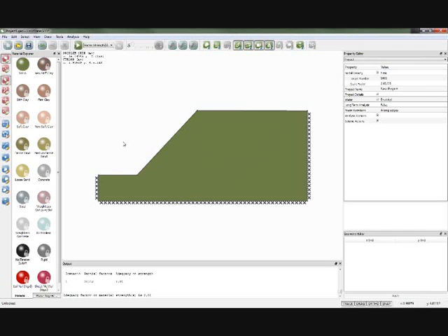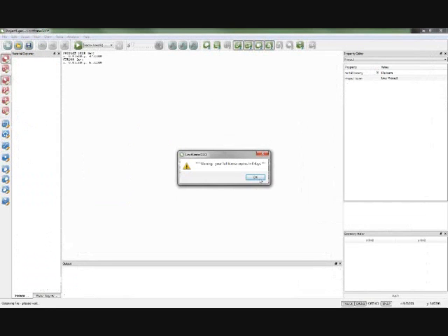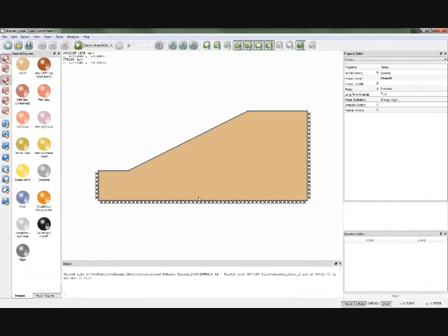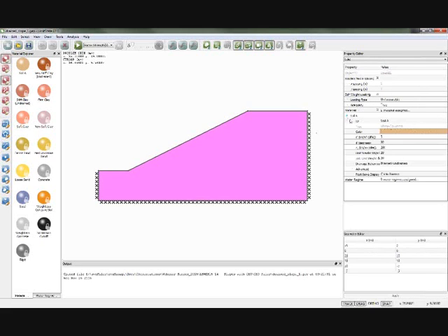Okay, so that's a simple undrained slope, which we could compare to Taylor's slip method, and we'll look at that a little bit later. What I'll do now is do a comparison with a method of slices solution. So I've constructed a model that replicates an example from the textbook by Whitlow. He gave a few examples of method of slices, and it's a slope of this angle. If I click on this body here, the soil that was analysed in the book had a c' of 5 and a phi of 30 and a unit weight of 20.